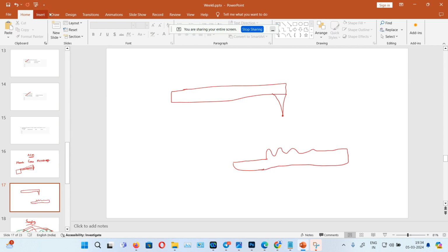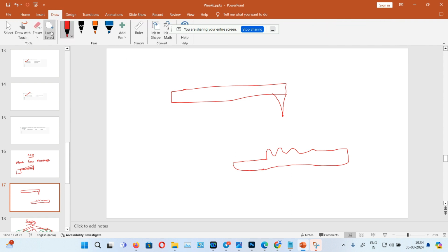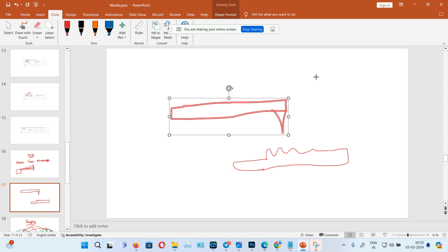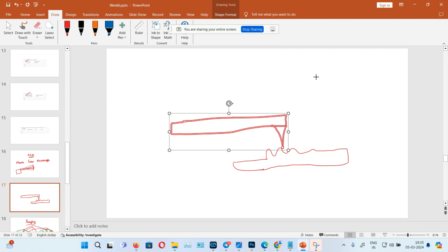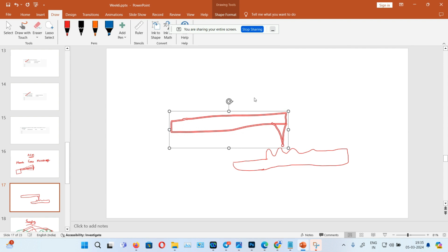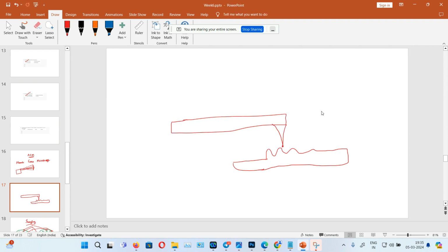So what we will do, we will move the cantilever tip towards this specimen, and either we will touch the tip to the specimen or we will go very near to it. When it goes very near to the specimen, there will be some interaction.